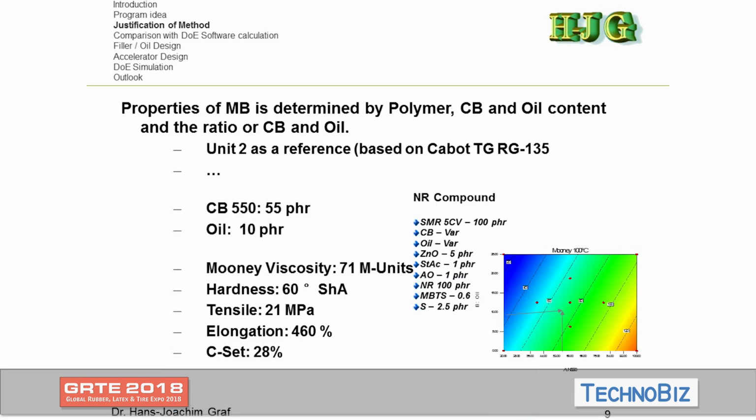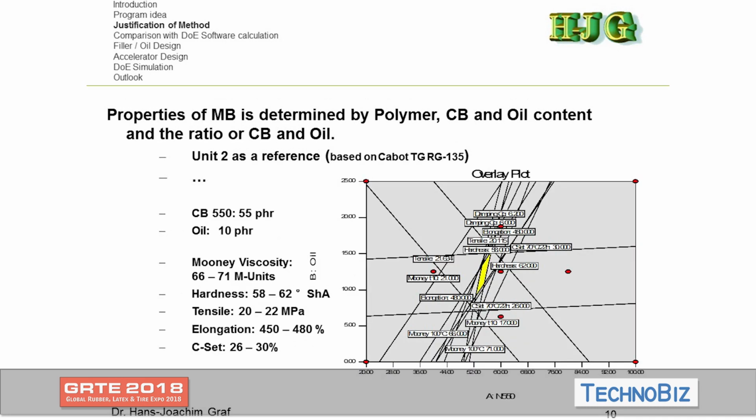And when you go in the old compounding charts and try to follow that, you see here a linear response surface lines, which are telling you, first of all, that the relation of carbon black and oil in this case has a linear relation to most of the properties, if not all of the properties. So that means first order regression may be justified even by that.